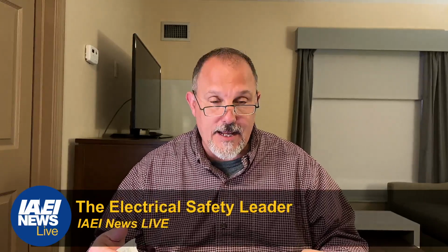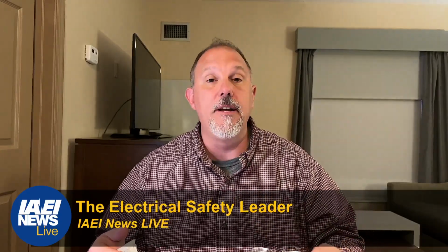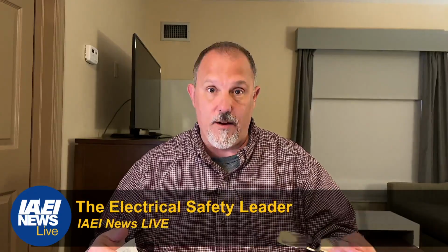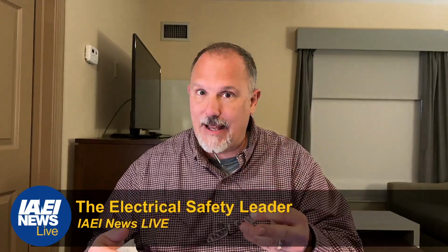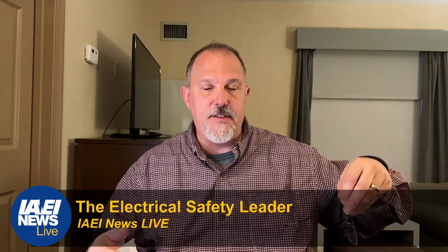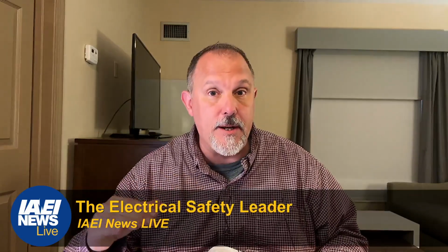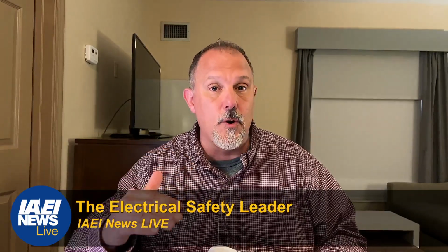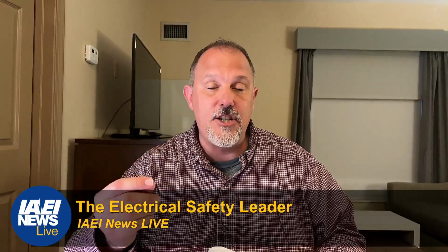Anywhere you see the acronym GFCI or the words ground fault circuit interrupter, that implies a Class A device because by definition and because of the new 240.7 requirements, it's required to be listed, period. I don't need to say the words listed GFCI. The moment I say GFCI, I'm implying listing.